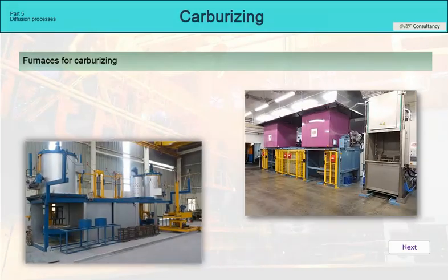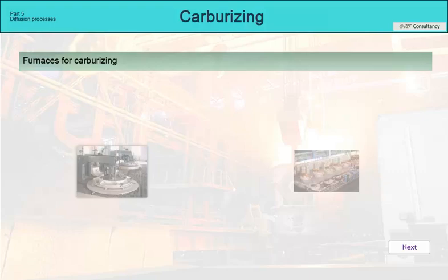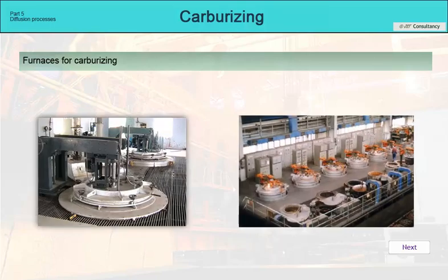However, in many cases, shaft furnaces that were manufactured in the 1980s or 1990s are still found. All of these devices operate on a similar principle, both in terms of the endoatmosphere and the control of the carbon potential. Only the control of the technology is at a significantly higher level.